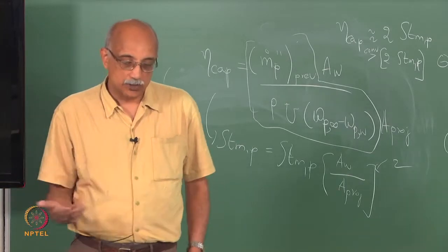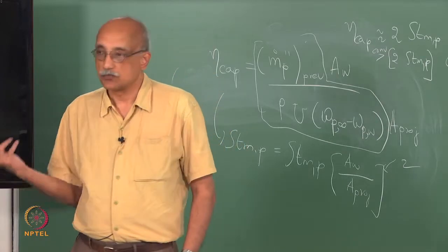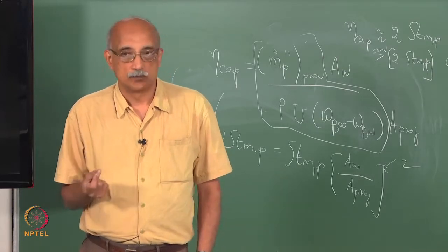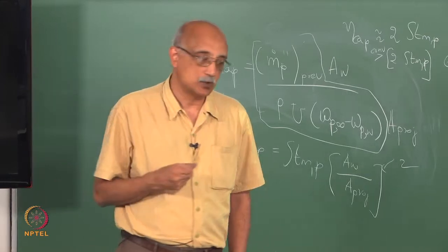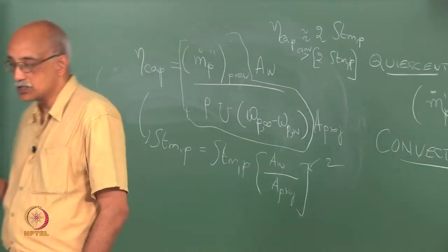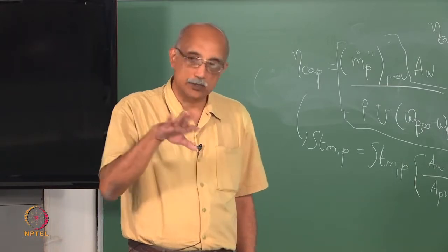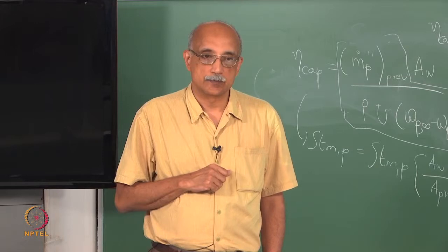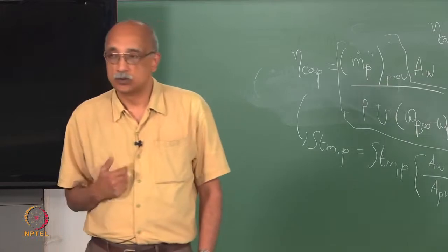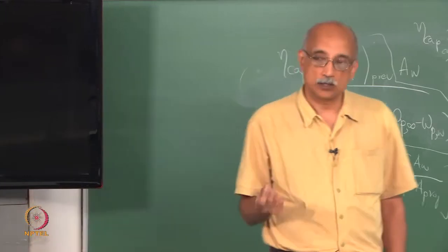All right, so after we talked about adhesion and cohesion, the last topic that we covered was the various transport phenomena that affect particle behavior. In the finest sizes, we talked about diffusion, Brownian diffusion, as being the predominant mode of transport of particles, particularly in the nano size range and the submicron size range. Electrostatic effects come into play just above the nano size in the submicron size range. And then in the intermediate size range, you have convective flow and phoretic flow as important transport mechanisms for particles.